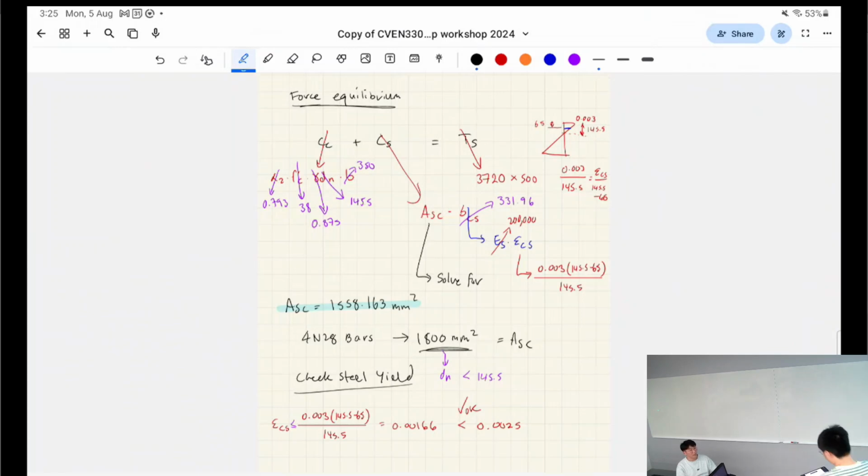Hey man, what's up? Just want to ask about the flexure stuff, right? Assuming that, for example, for the uniform load, the 1.35G is the governing one, but for the point load, it's like assuming it's a live load, right? So it's like 1.2 and 1.35. What do we choose then?